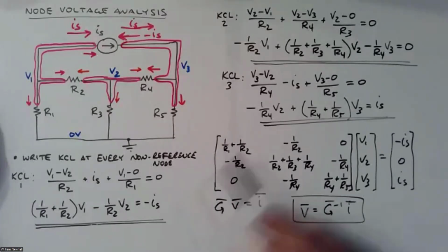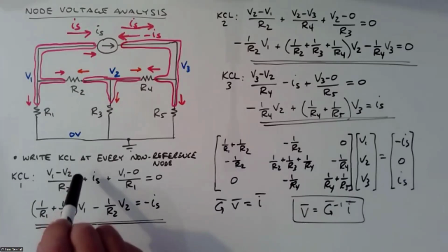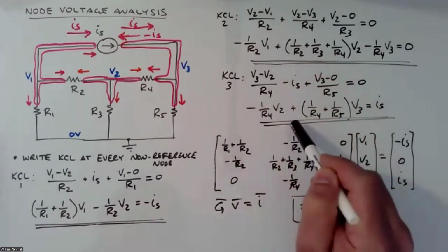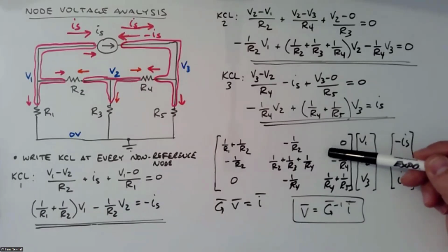You're also welcome to put these equations into an equation solver on your calculator, or whatever software you have that can solve simultaneous linear equations. But I sort of stepped away from node voltage analysis. Node voltage analysis really is writing the 3 KCL equations and then solving those equations.